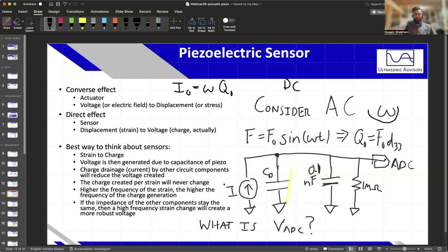So the charge rate. If you do a circuit simulation, you want to divide this amplitude, whatever you set it at, by frequency. If you have a constant displacement excitation, or a constant velocity excitation, you wouldn't need this component. But typically, with a circuit simulation with constant force, you need to divide by frequency to say there's a constant charge being put into the system. Because the frequency is changing, as you go to higher frequency you're generating the same charge, but the same charge has to be delivered faster, so we need to divide by frequency.